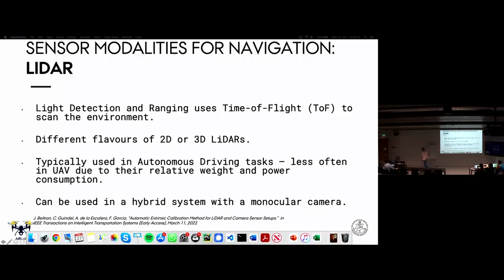still require. So if you were thinking about having a UAV that needs to fly, for example, for 10 minutes, obviously the motors that are keeping the UAV in the air are going to be the most power-hungry part of the system. And what's going to happen is that you're going to drain a lot more power. If you have a heavier sensor, and you also have to power it and have the laser beam running at really crazy speeds, then it also brings the battery life down quite a bit.